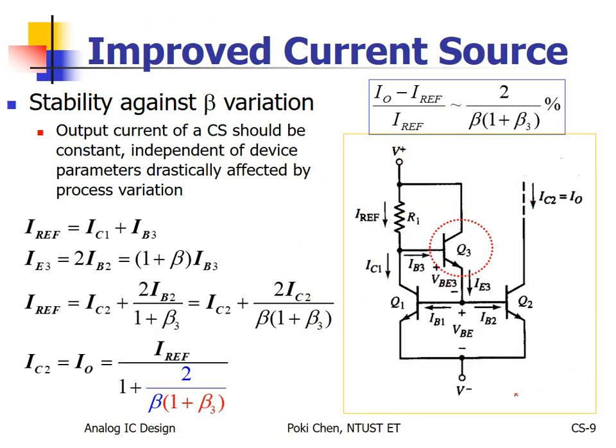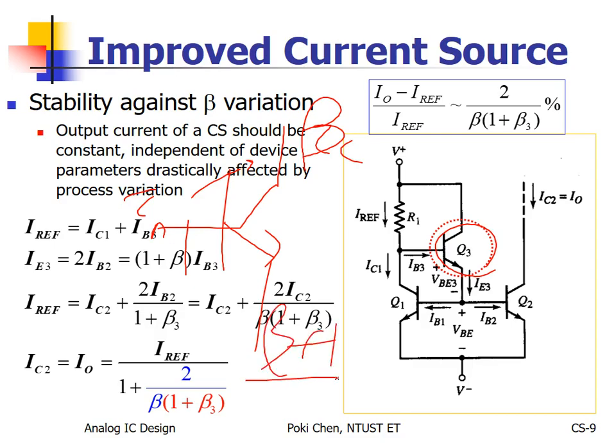Okay, so what is the function of Q3? I told you already, from the very beginning, BJT is used to amplify IB to IC or to IE, because 1 here, beta there, and beta plus 1 at the E terminal. Right? So if you look from base to collector or base to emitter, it looks like an amplifier. But here it is not directly related to amplification. No. On the contrary, we would like to use it in a reversed way.